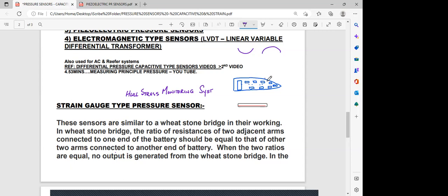So if you are going to have these boxes like this on your port side, then in the in-between position of these two, you're going to have the corresponding one on your starboard side. And then you're going to have the bow one, because your bow bends very, very rapidly. If you're standing on the bridge of any big ship and you're going through rough weather, you will find the forecastle forward mast going up and down like this. That is why you have that rocking motion whenever you're going through rough weather. That is the ship bending because of that particular thing.